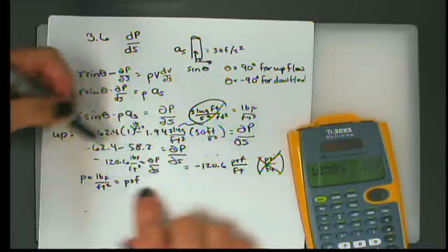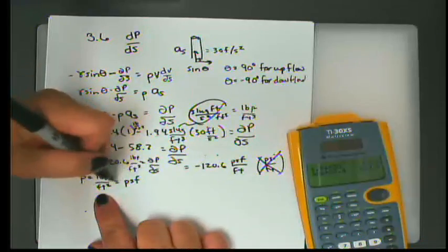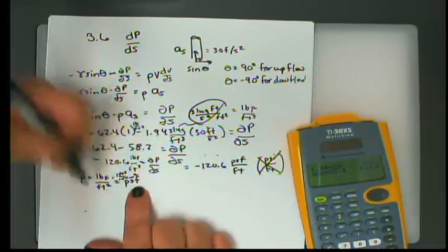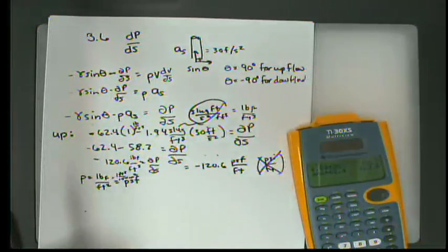Okay, because if we had done that, we would have had to go PSF, or pounds per foot squared, times 1 foot squared per 144 inches squared to get a PSI per foot, and so this number would actually be divided by 144 in order to be correctly reported in PSI per foot. So just making a point.